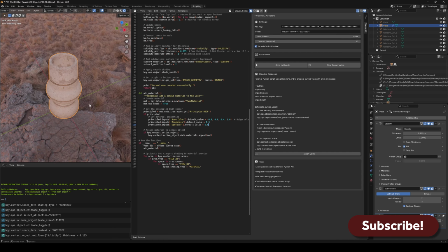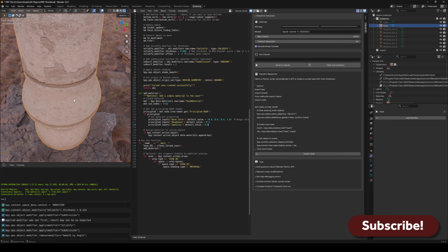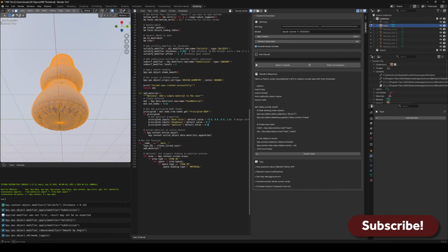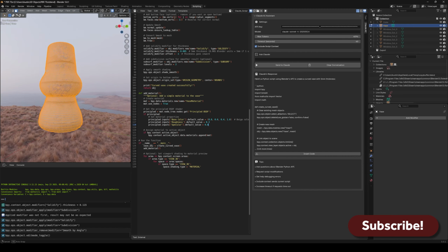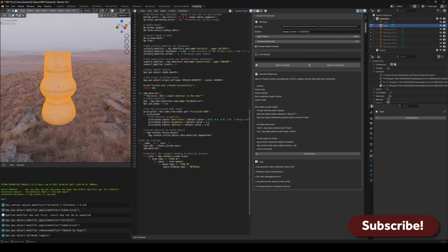And then before you export this to be 3D printed, you have to come in here and apply the modifiers in the correct order. I don't need the smooth. And then from here, you can look at the topology. Very interesting. You could also decimate this.